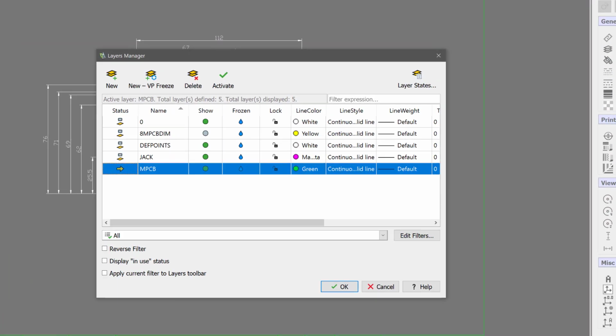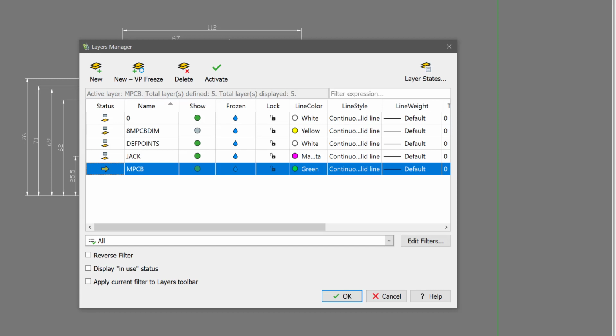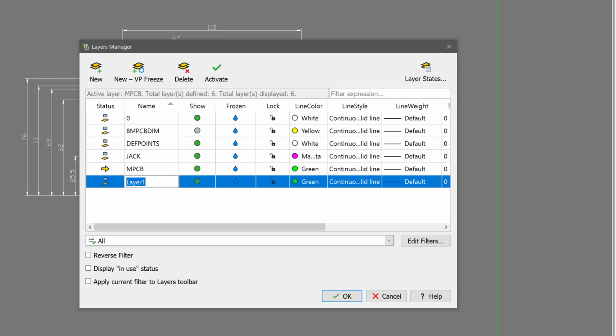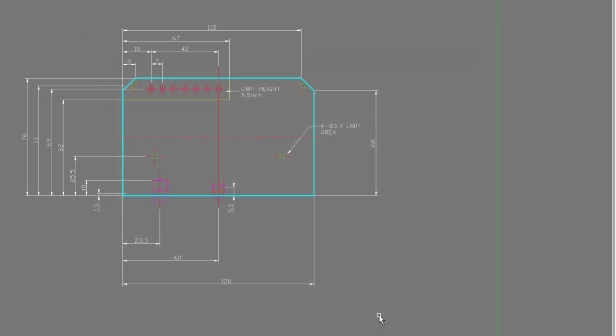So if you create, for one specific PCB layout software, a board outline on the 00 layer, and when you create inside your software this board outline as a closed polygon and place it on this layer, when you import the DXF inside the PCB layout software, specifically in PADS Layout, it will automatically become an intelligent board outline.